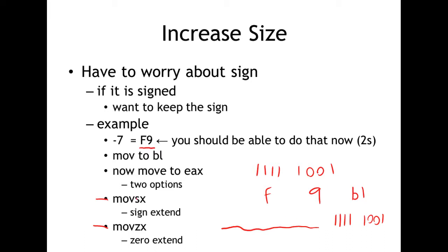Well, what the sign extend is going to do is look at the most significant bit, and then extend that bit. If we look at this value, the most significant bit is a 1, so it's going to extend that value. That way, when we fill up that larger register, we fill it up with the appropriate sign, because now we have a full 32 bits, and this becomes the most significant bit, and we need to make sure it's set the same as our original value.